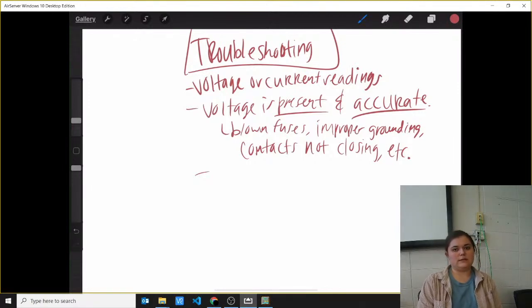So that's why you'd see a lot of VFDs in power plants. And motor drives provide a number of performance benefits over standard motor control systems. The benefits of motor drives include significant energy savings, precise control of motor speed and torque, and elimination of high starting currents and high transient voltages resulting from large motors turning on and off, because motor drives ramp up motor speed when starting and ramp down motor speed when stopping.